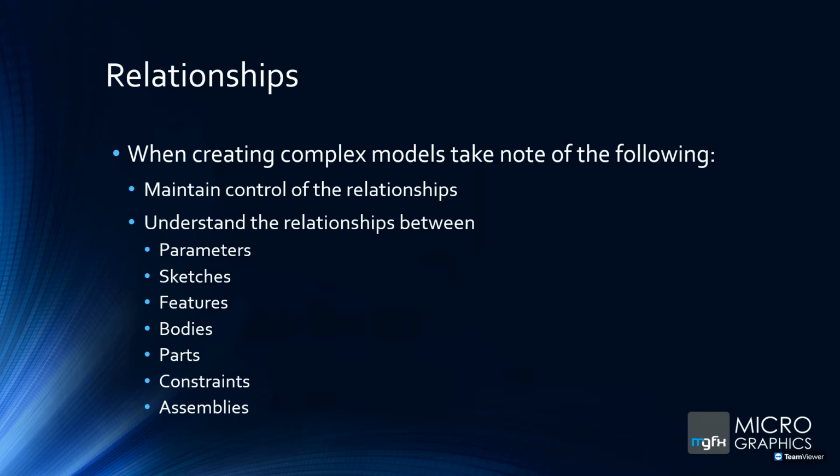And we've got to be cognizant of that fact because if, for instance, that hole disappears, we delete that hole for whatever reason, the design doesn't need it anymore. But is anything in that additional sketch that I've created attached or connected to that hole? Maybe I've created another hole which is now referenced to that hole. I delete the first hole. Now we've lost that relationship to the second hole in that sketch. So we need to be careful of that.